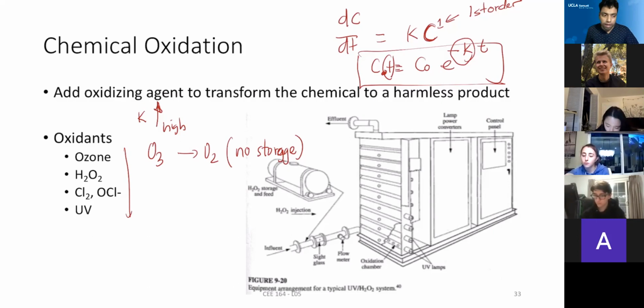So now, leaving that behind, there are two other things: hydrogen peroxide and chlorine. Between those two, hydrogen peroxide is reactive. Chlorine, the chlorine gas, the OCl, is not that reactive. So why is it important? This is important for wastewater treatment plants. Hydrogen peroxide is highly water soluble, so it's very easy to mix. That means you don't have to worry, like with UV light, whether you can mix or whether all the pollutants can be reacted easily or not.